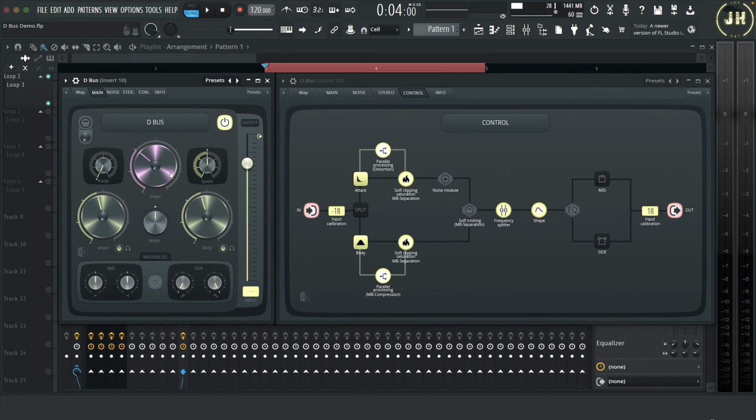As I mentioned, you control the shape knob together with the pump and the speed knob. The pump knob controls the amount of attenuation directly after the transient, which emphasizes the transient without increasing the level. And with the speed knob, higher values result in a snappier transient modification, and lower values result in smoother curves.